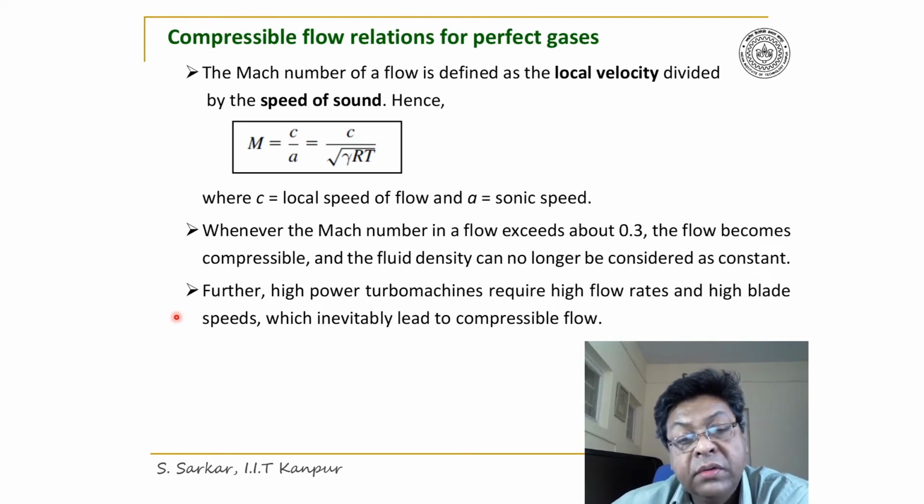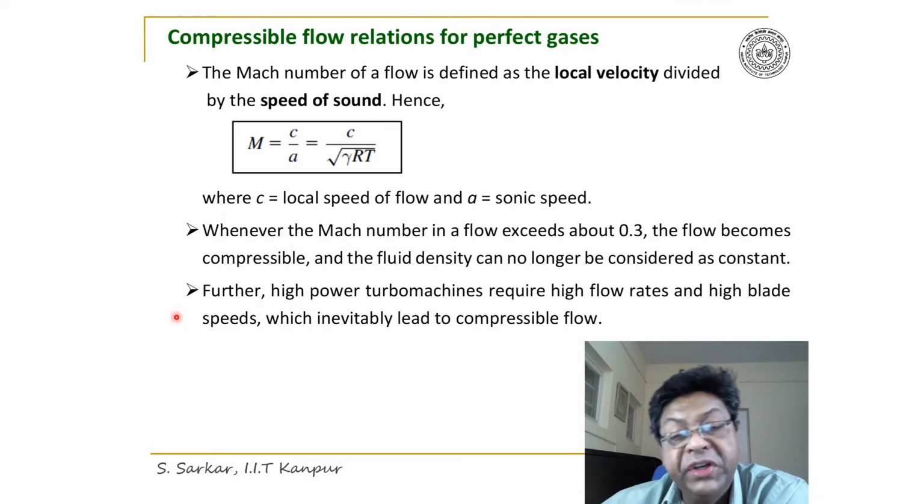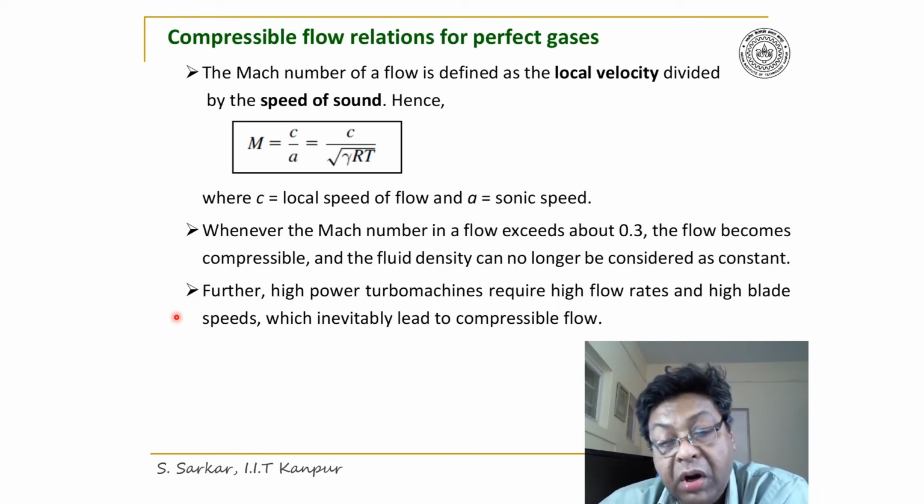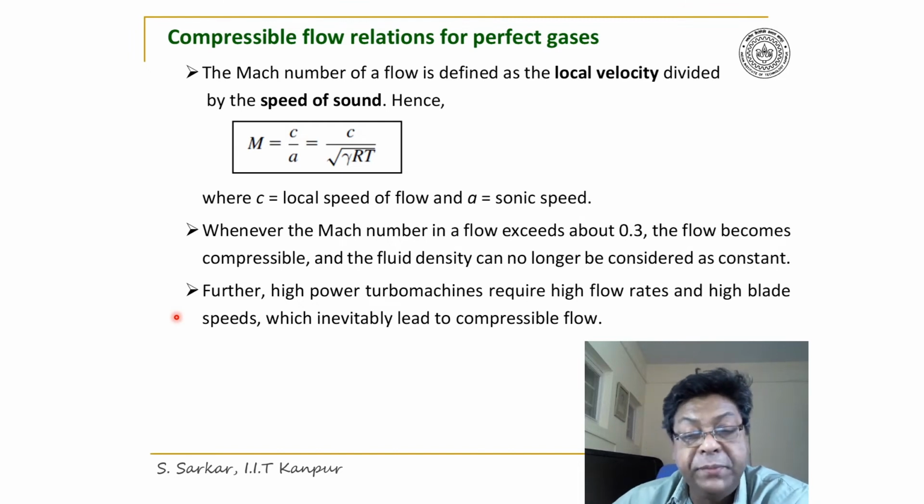Furthermore, high power turbomachinery requires high flow rate and high blade speeds, which invariably leads to compressibility. So for compressors or turbines of high power and speed, the flow must be treated as compressible.